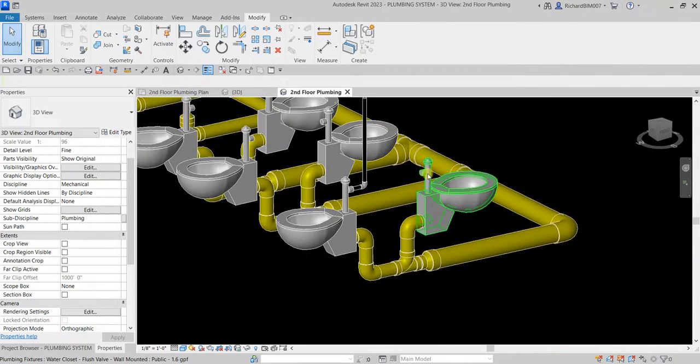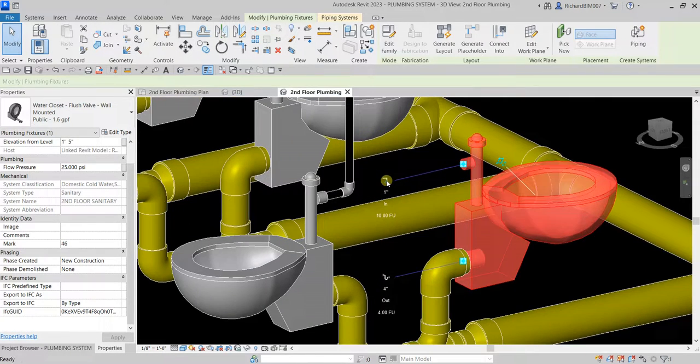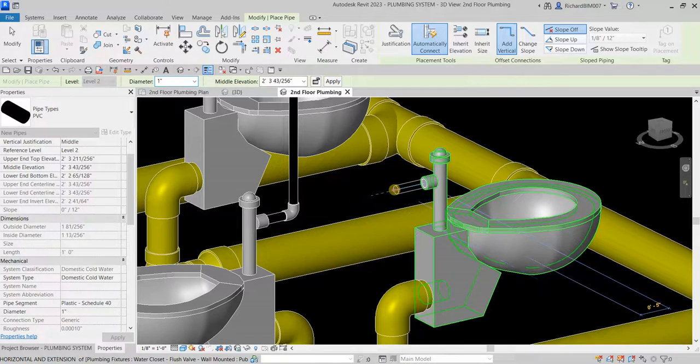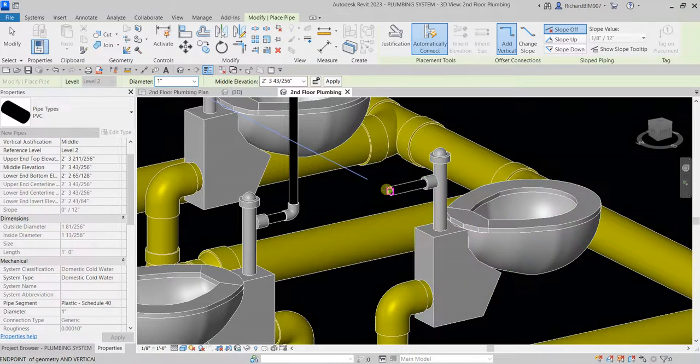Anyway, the next thing that I'm going to do here is create another pipe on the other side here. So let's click this one. Let's create another one. Okay, make sure the direction is like this. You can hold your shift to make sure it's straight. Okay, so I click that.